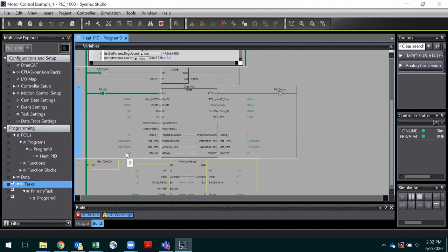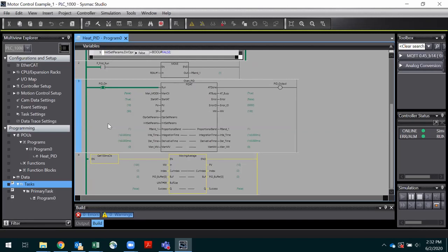Now you can flip the start AT bit. The auto tune won't override if you have 0 on any of those parameters. They have to be non-zero to be auto tuned. I've never tried the other way. I just know that setting them to 0 disables either integral or derivative mode. That'd be something I could find out pretty easily. So I triggered the start AT.